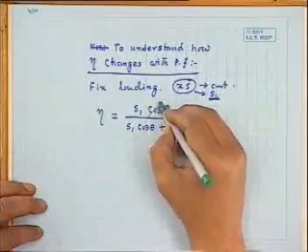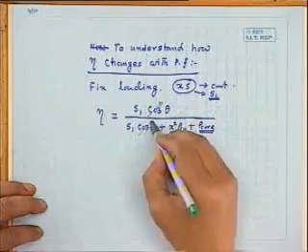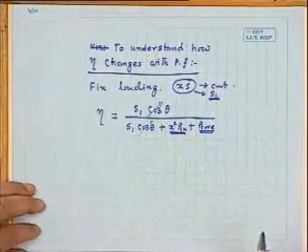Now, if you keep the loading on the transformer constant, what will happen to the copper loss? Copper loss at a particular degree of loading remains constant, no matter how you change power factor. That is x into S you are keeping constant, which I am calling S1 here. So output power will be S1 cosine theta. Here what I am changing is only the cosine theta. This is the variable part.